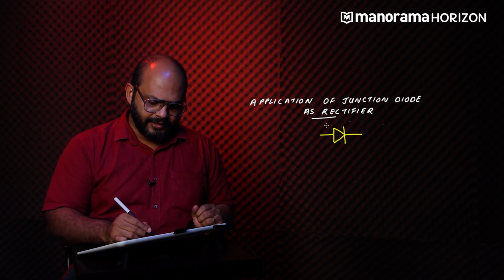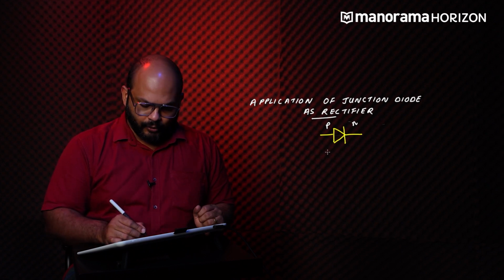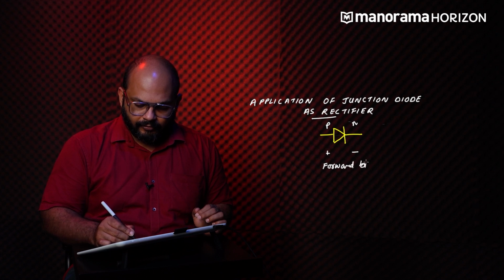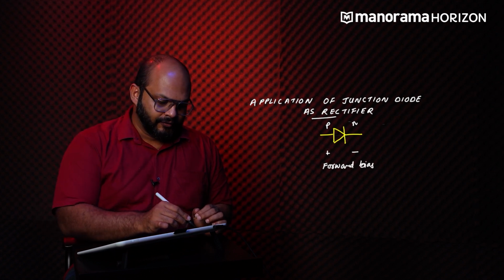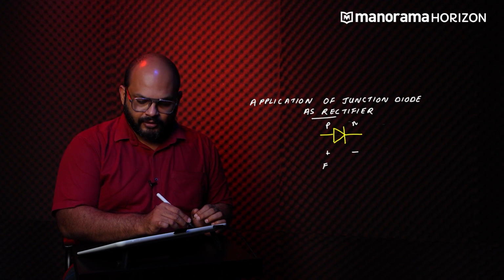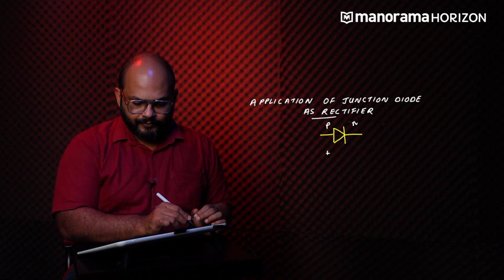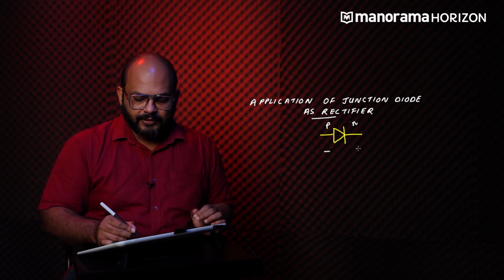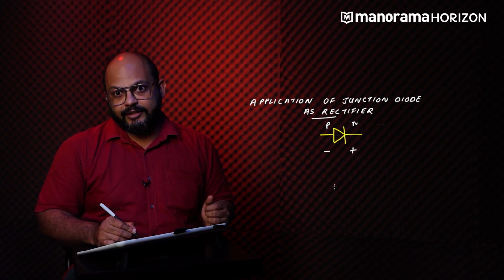And this is the P side, and this is the N side. If we apply voltage like so, that is positive voltage on the P side and negative on the N side, this is what we call forward bias. And if we were to reverse the arrangement, that is, we are applying negative voltage on the P side and positive voltage on the N side, this is what we call a reverse bias.